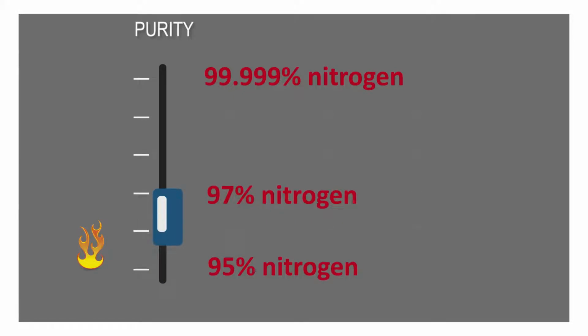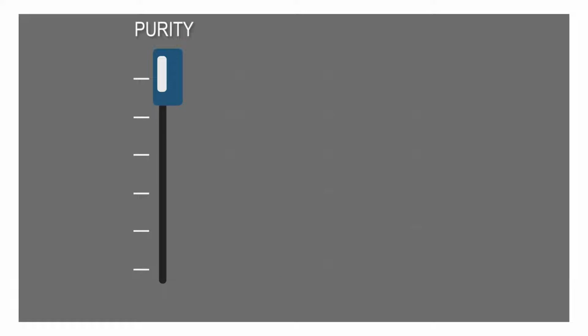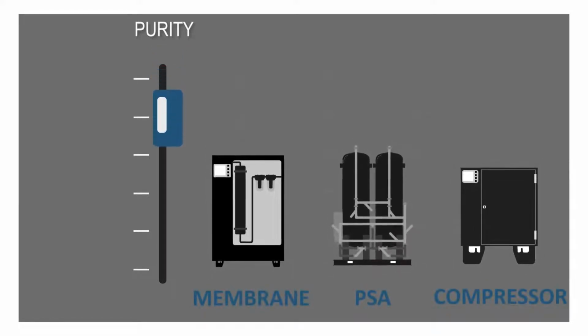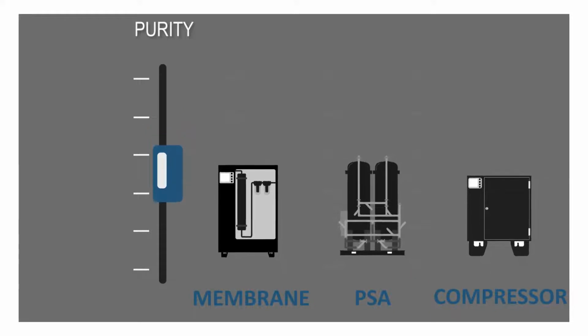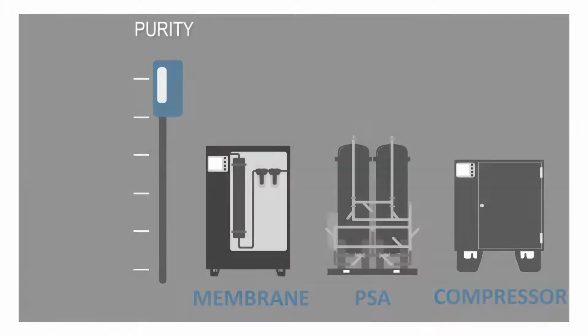If the nitrogen will be used for heat treating metals, for example, the required purity could be up to 99.999%, which is 10 parts per million of residual oxygen. It is important to know the purity your process can tolerate because both the capital cost and the operating costs of a nitrogen generator rise steeply as the purity increases. Note here that nitrogen from bulk liquid always comes at high purity, and the gas purity you may be used to is likely to be higher than that you would actually need. Your generator supplier can advise on this matter. And at Holtec we can help with industry references or a test plan to help you determine what purity you need.